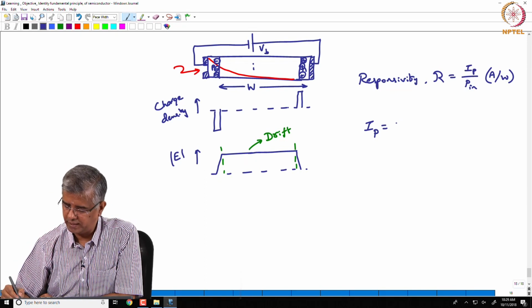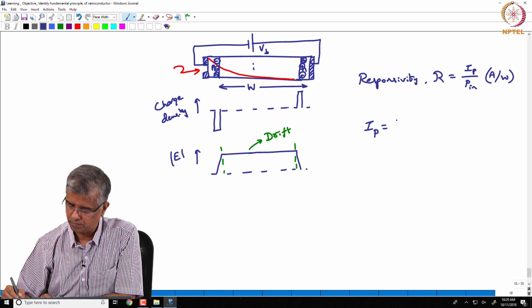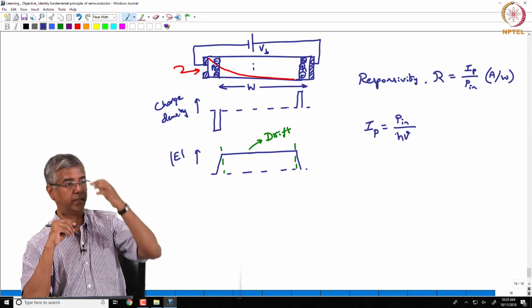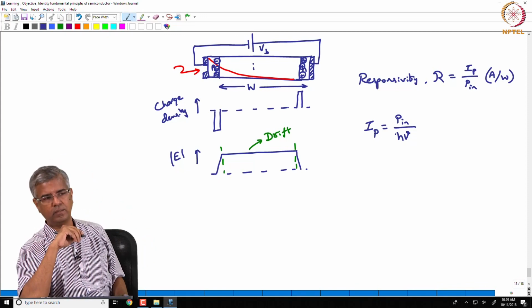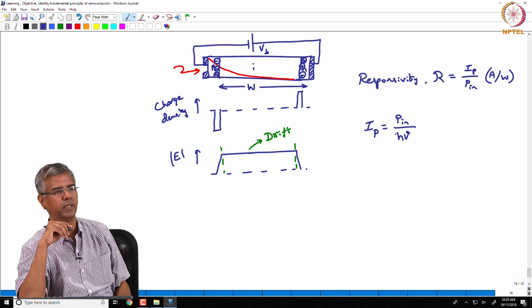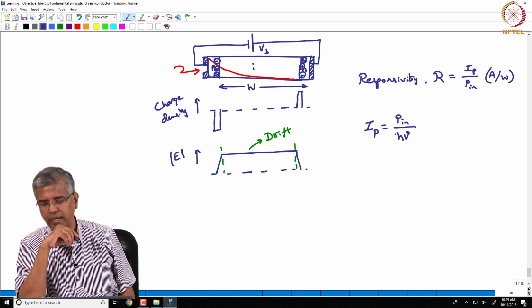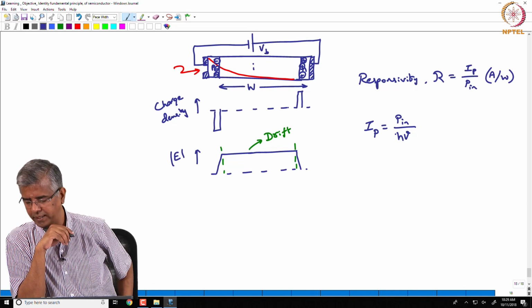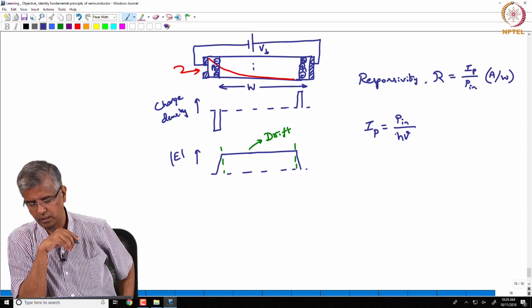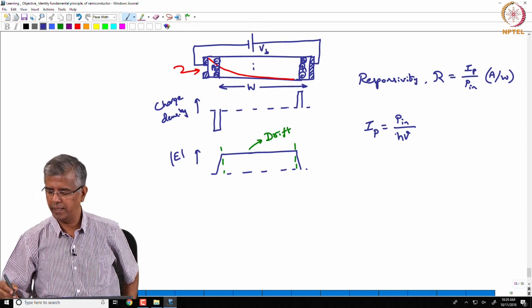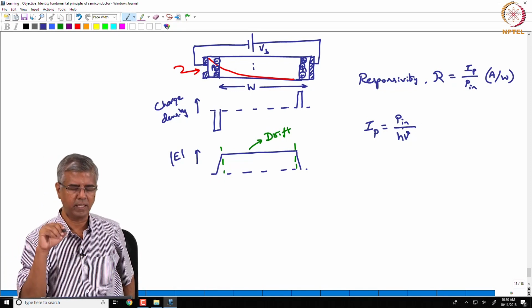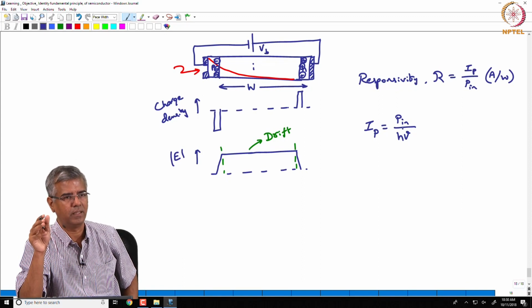So what exactly is happening when light falls on this photodiode? Now light falls on this photodiode at a certain rate, okay. That rate, that flux, is given by power over photon energy, right. So P in over h nu is the rate at which the photons are incident on this, and when they are incident on that material, which is a high index material, right.